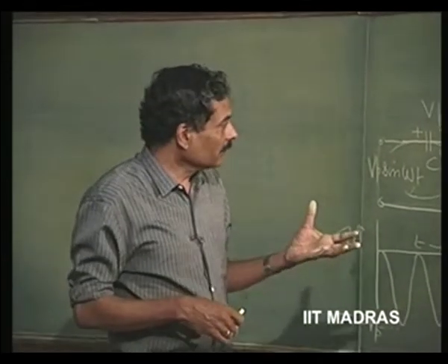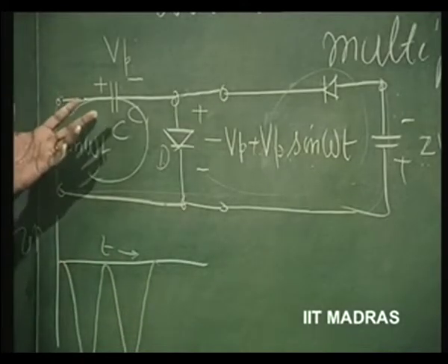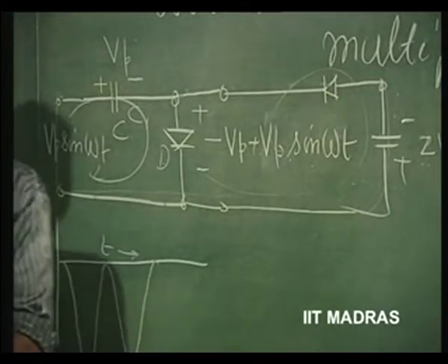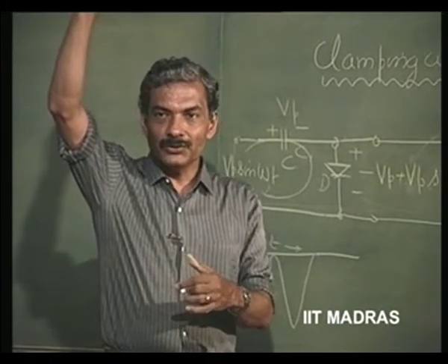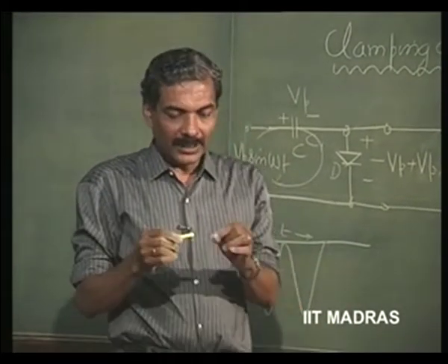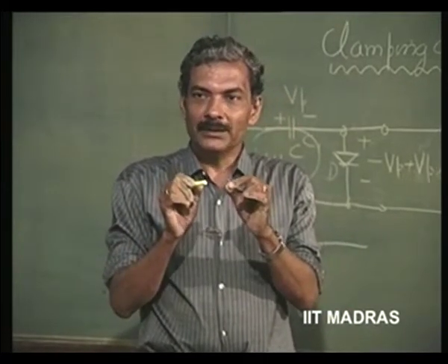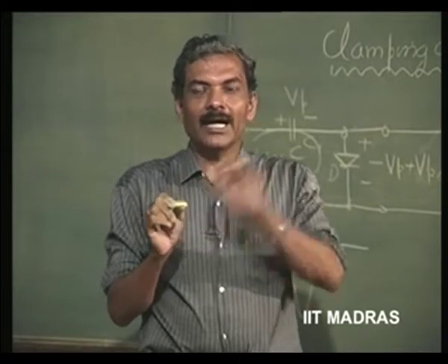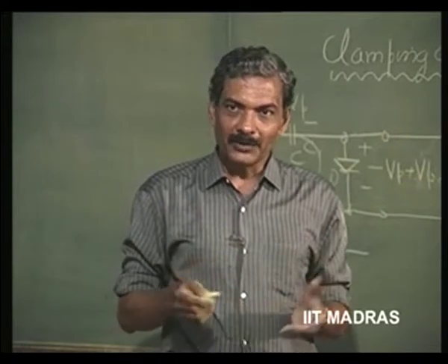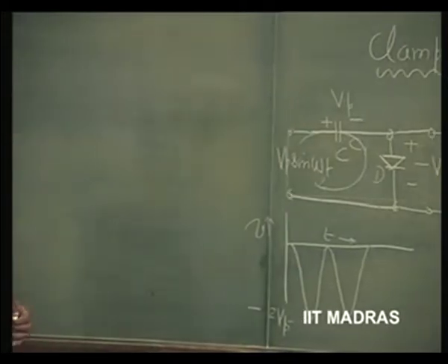So this gadget is nothing but just a diode in combination with a capacitor, and ultimately when you get, let us say, 1000 volts or 2000 volts from just a power line frequency, you can just connect it to a very sharp metal. There it will ionize the whole atmosphere and produce a large amount of negative ions. This is a very simple application of this voltage multiplier.